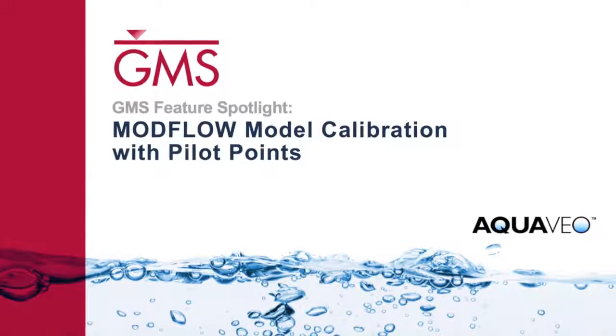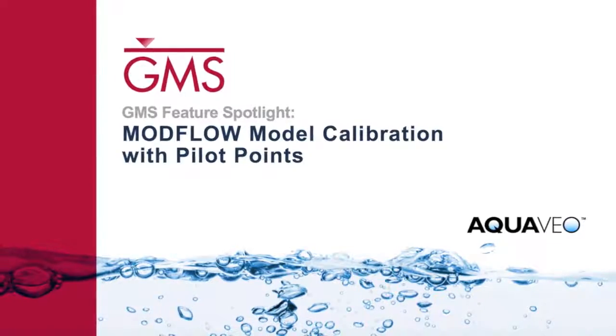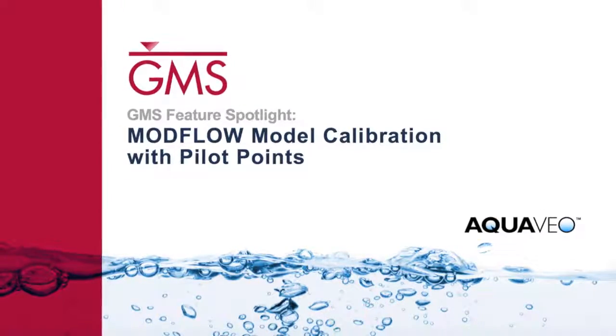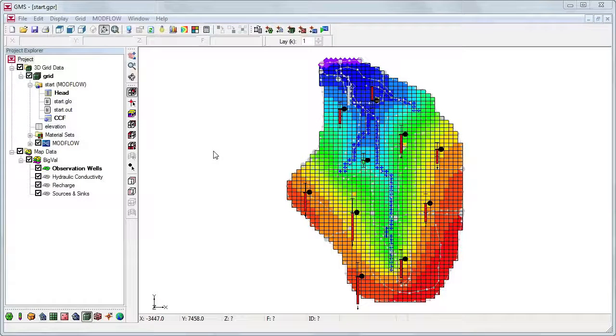In this demo, we'll calibrate a MODFLOW model using the parameter estimation model PEST and pilot points. Pilot points can be thought of as a 2D scalar dataset. This means that instead of creating a zone and having PEST estimate a single parameter value for the entire zone, parameter values vary within the zone and are interpolated from the pilot points.